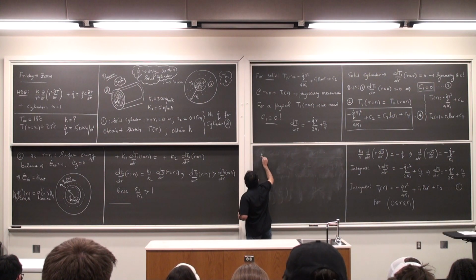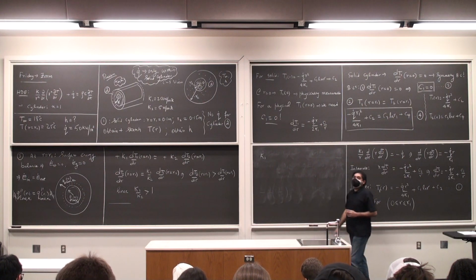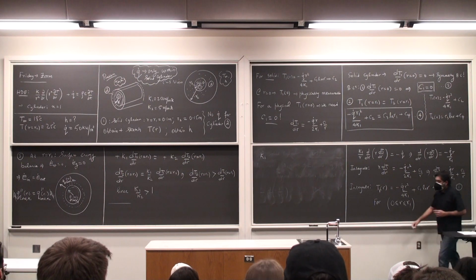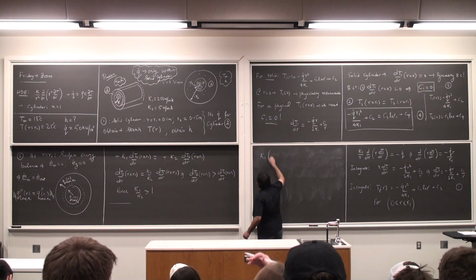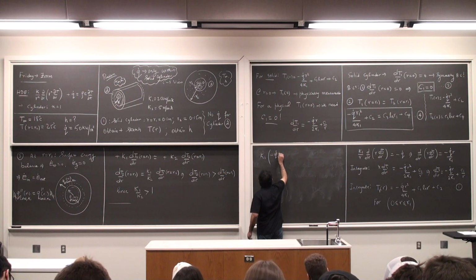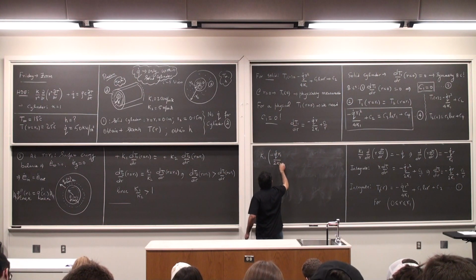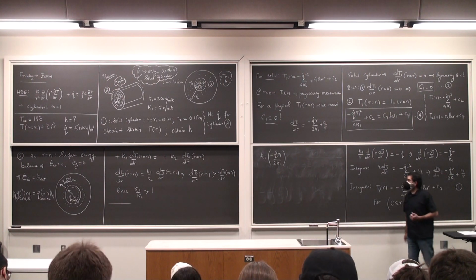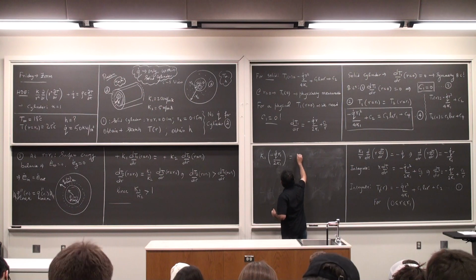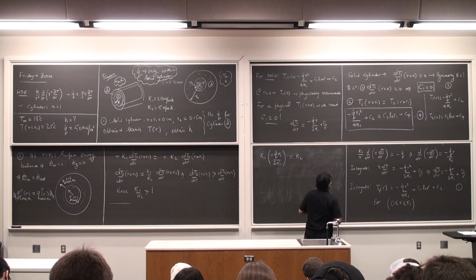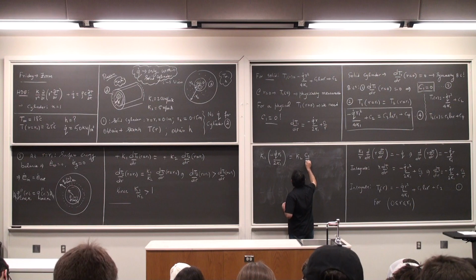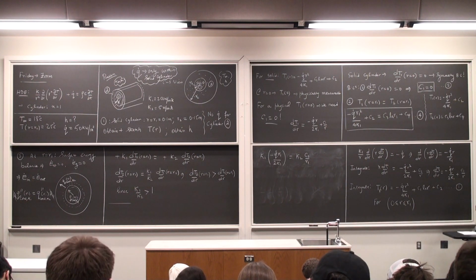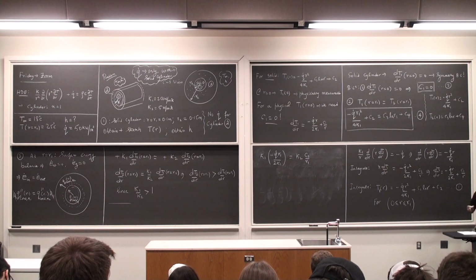So K1 dT1 by dr is minus Q dot times R1 by 2K1 after doing the substitutions. At R equals R1, this is equal to K2 times C3 by R1, which is the differentiation of logarithm of R is 1 by R. Okay? So I've directly performed the substitutions.